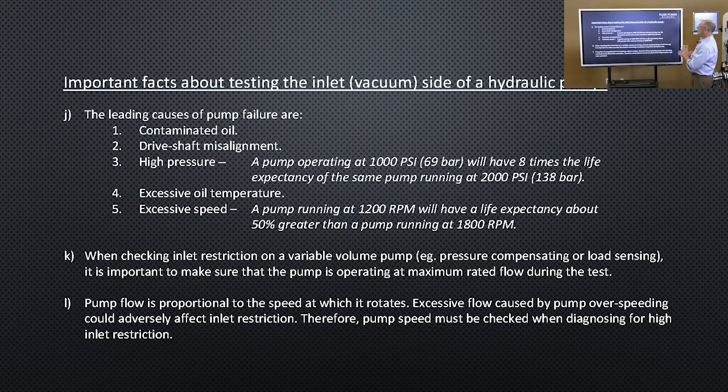Again, the leading causes of pump failure are contamination, the single leading cause of pump failure, shaft misalignment, high pressure, excessive oil temperature, and excessive speed.